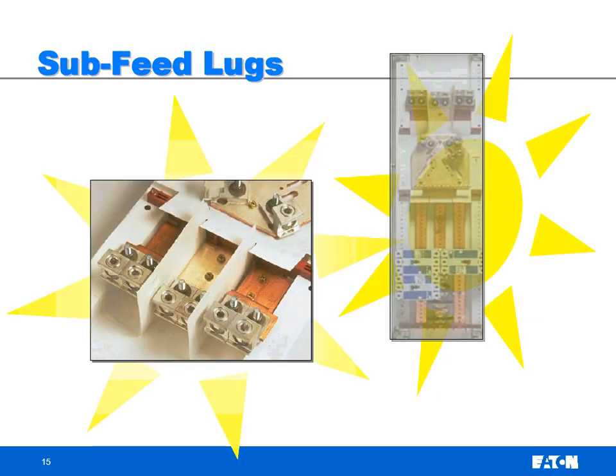Okay, this is just a visual. Normally you're going to have your bus bars, A phase, B phase, C phase, and where we normally may just put one lug to land one cable, we're going to put two. One cable lands here, feeds the panel, the other cable lands here and jumps over to the next panel. Physically, where these are located, here's your panel, here's some branch breakers, way on one end, either the top or the bottom.